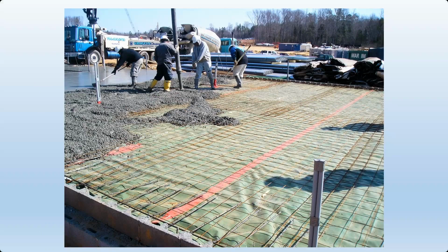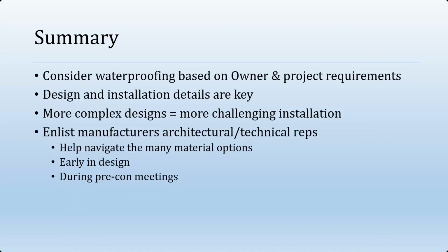So anyway, to close out here, we just want to consider waterproofing based on owner and project requirements. Design and installation details are very, very important. The more complex the design, the more challenging the installation. And by all means, enlist the manufacturer's technical reps to help you with the specs and drawing development. That's what they're there for. As early in the design process as possible would be great. And certainly discussion during pre-construction meetings, as we talked about those conditions that unfortunately befell us on a couple of projects, but that's really the onus of the GC or the CM.